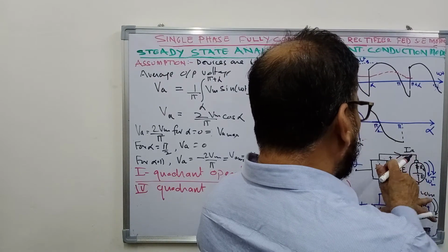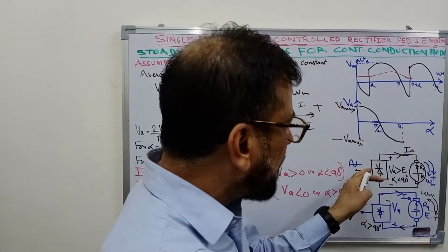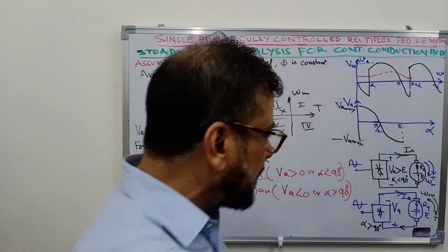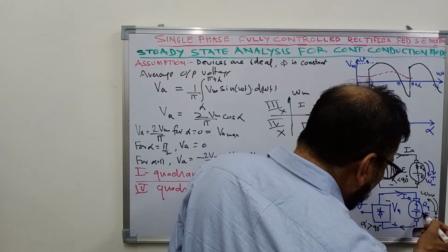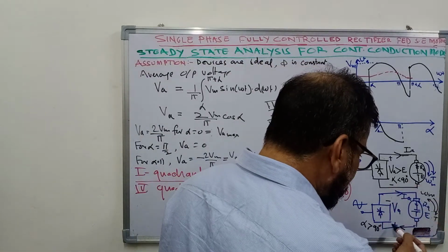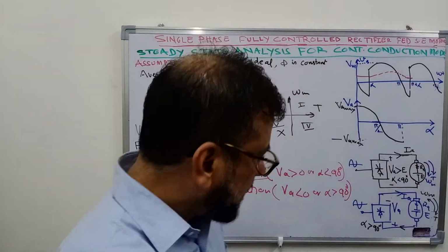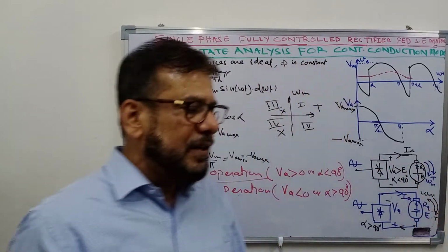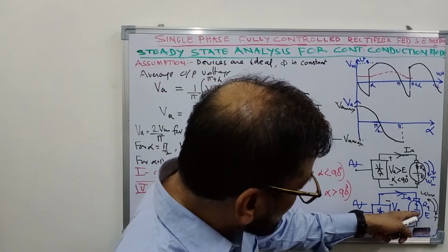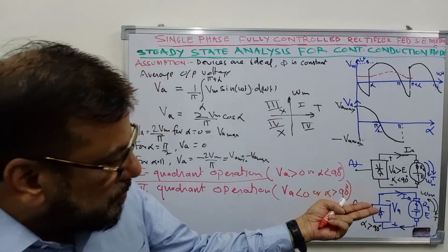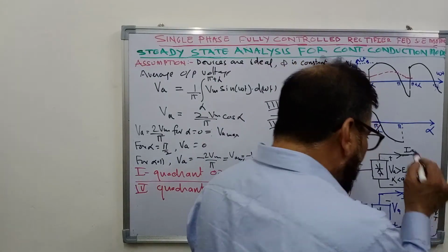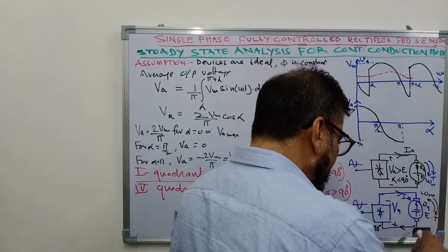If this is the situation and you have just reversed alpha, then current can never flow in the positive direction. For current to become positive with alpha more than 90 degrees, the only possibility is that the polarity of back EMF, or armature EMF, should reverse. This is positive, trying to flow the current in the reverse direction, but for current to flow in the positive direction, the polarity of the back EMF has to reverse. It has to become negative, as shown in this figure. So the polarity of E has to be opposite to what it was in forward motoring mode, and the value of E should be more than VA for current to flow in the clockwise direction.